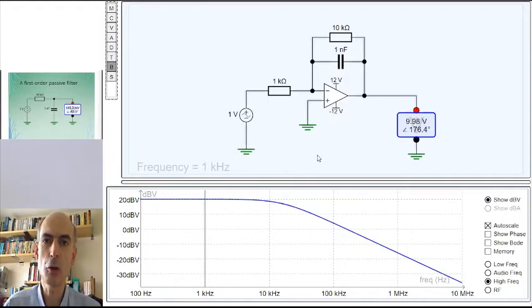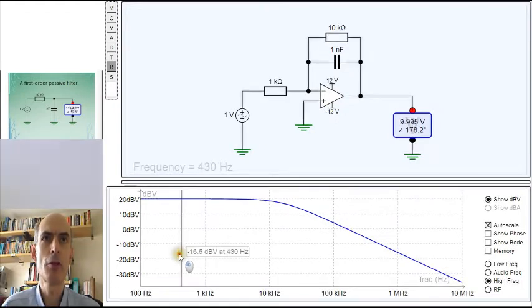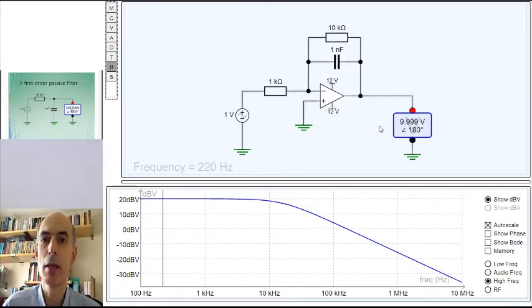It's clearly a more complicated circuit than the simple RC circuit that we saw before, which raises the question, why would anybody build this circuit rather than just use a much simpler passive filter which doesn't require a power supply and will be much cheaper to build? Well, you might be able to see one reason already, and that is at low frequencies, this filter has a gain of 20 dB. Active filters can provide gain as well as this frequency-dependent response.